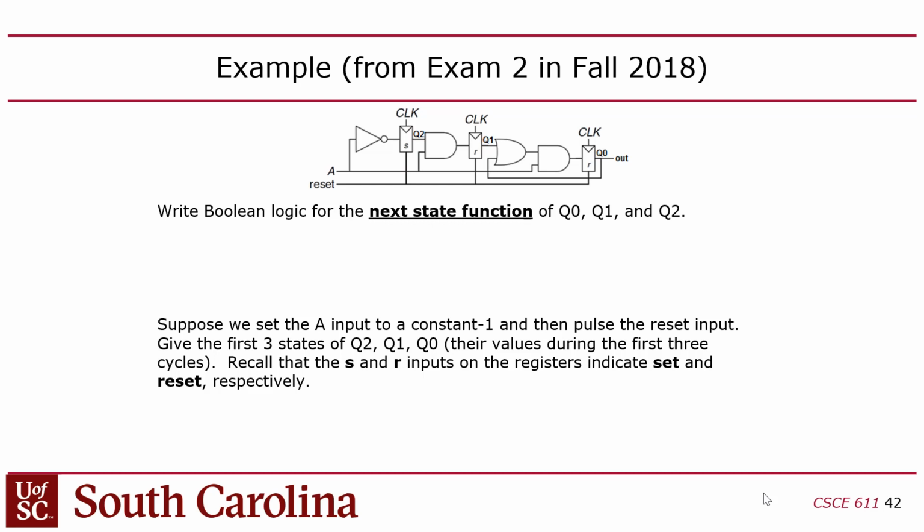In this case, you have 3 flip-flops. You'd have to calculate the contamination delay and the propagation delay between the first 2, and the second 2. Then do we have something involving the third? The third flip-flop feeds back into itself, so you have a path from this one back to itself.